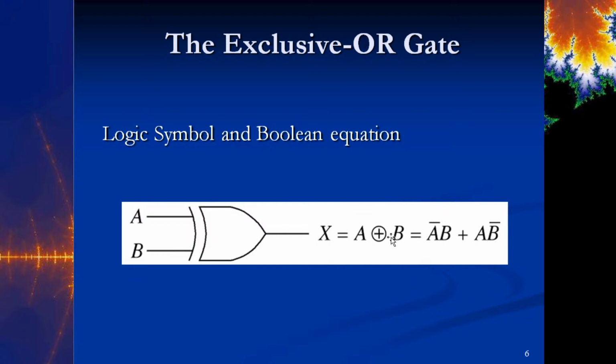But if we say A or B exclusive ORed, that's probably how I would say it. If you circle the plus sign, that makes it exclusive. And then obviously we just showed how you could write this out in regular Boolean. So that's a very specific equation for the exclusive OR situation. Okay?